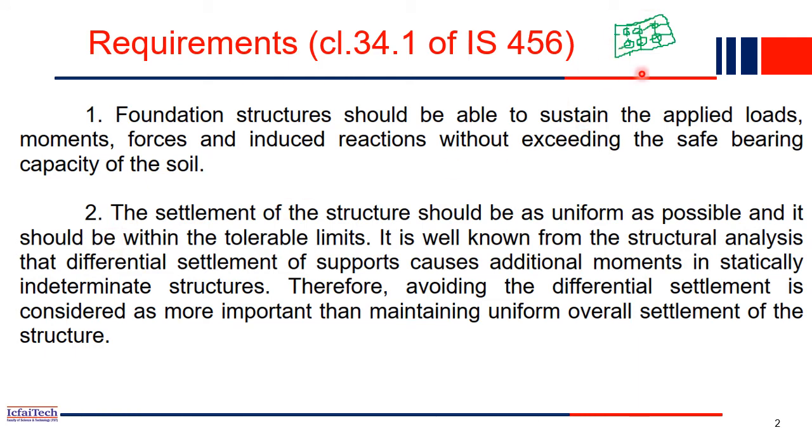If there is differential settlement, then this will cause extra forces on a structure, which may fail. Because of that, the structure may fail also. So the settlement of the structure should be as uniform as possible, and it should be within the limits, right? We will have some specific limits, so the settlement should not cross that limit.